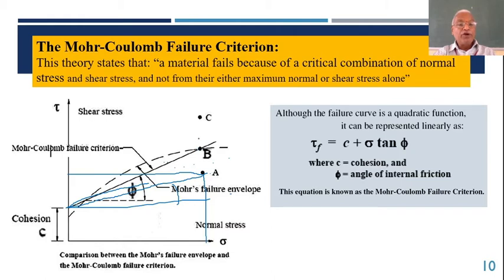And then if you go beyond that, if you try to analyze C, the C never exists, because the moment it goes beyond B, anywhere here, the shear stress is slightly more than the critical combination, the failure will occur. So there is no point to go ahead. Try to understand that. Below this particular dotted line, you get all combinations which are safe. On the line, it is all critical combination, and beyond that, you don't get any combination at all.